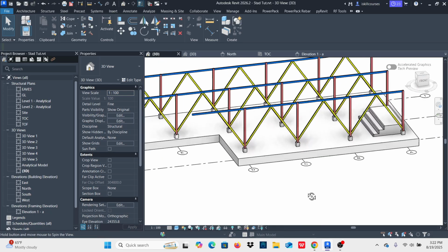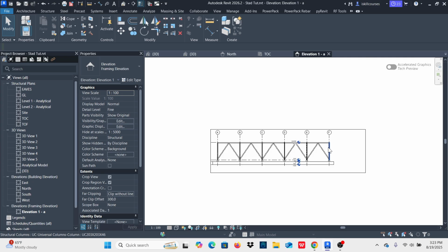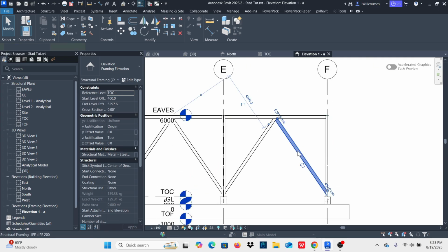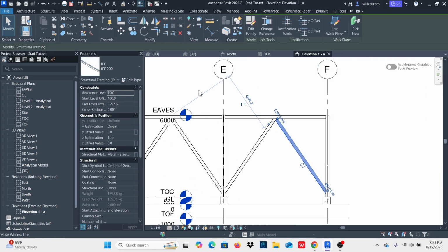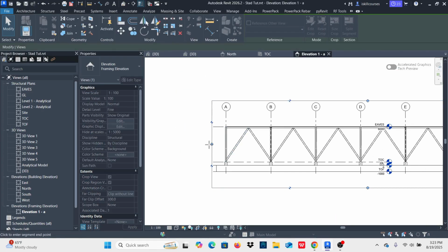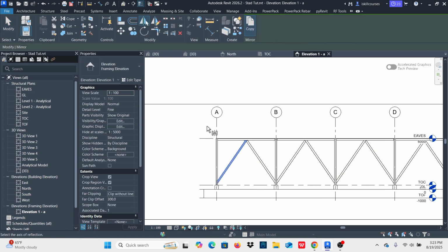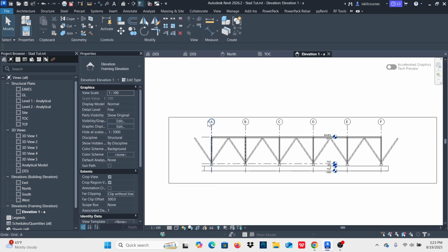And before I do that, actually, I forgot that I'm supposed to add one member here. So I'll go back there and let me just mirror this one about this point. So I'll do that and just click on mirror and mirror like that. Let me also mirror this one by dragging it there. I'll select that member and I'll click there and simply mirror it right there.